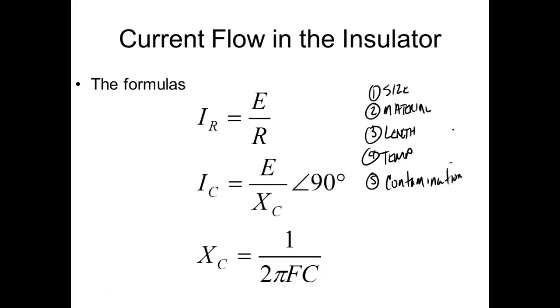So the jacket is not intended to be insulated. And that's not exactly true. Sometimes the insulator and the jacket are the same thing. But a true cable that has two or more conductors inside of it, the conductors will have their own insulator, and then they'll be encapsulated in another plastic sheet that is truly a jacket.